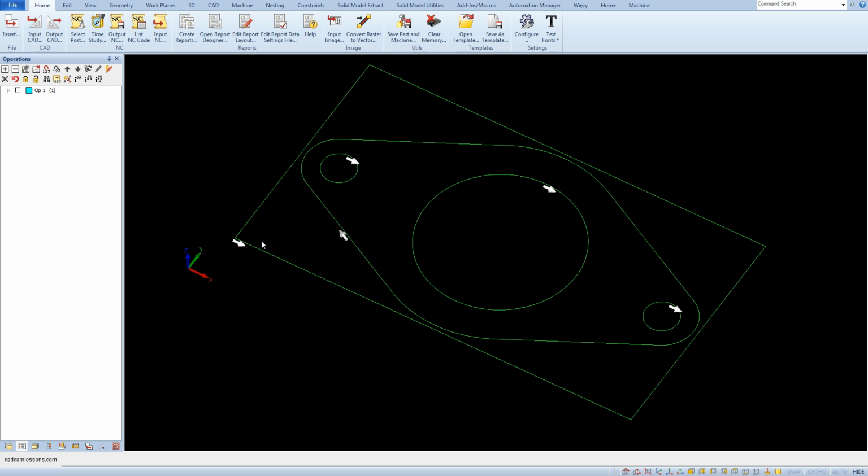Various approaches are used in various CAM systems. In one, the origin of the coordinate system is defined relative to the geometry. It means we indicate the place on the model in which the base is to be. In other CAM systems, the origin of the coordinate system is fixed and the geometry is set to it. This is also the case for Alphacam. So, here we have to move the geometry to the origin of the coordinate system, not vice versa.